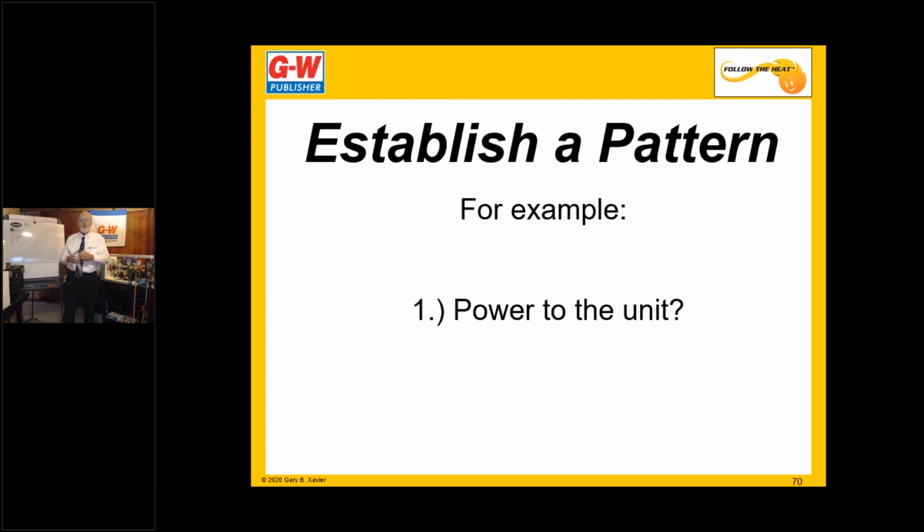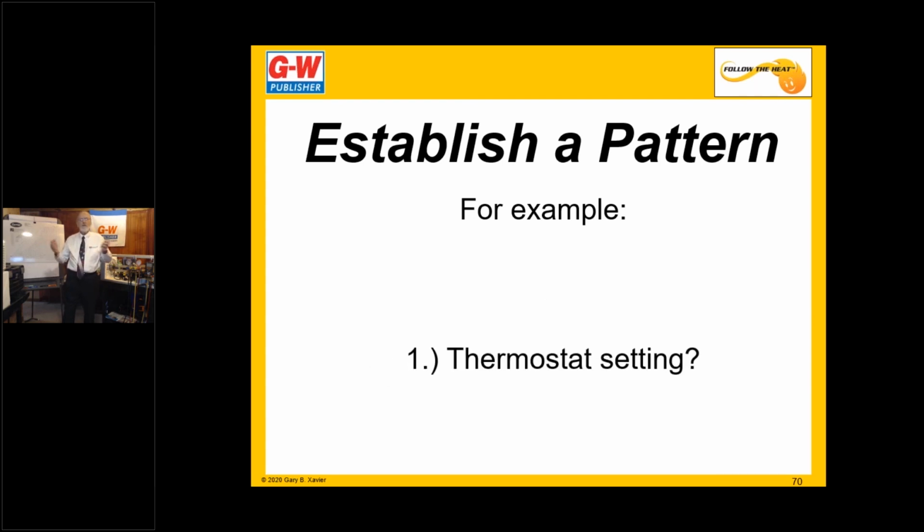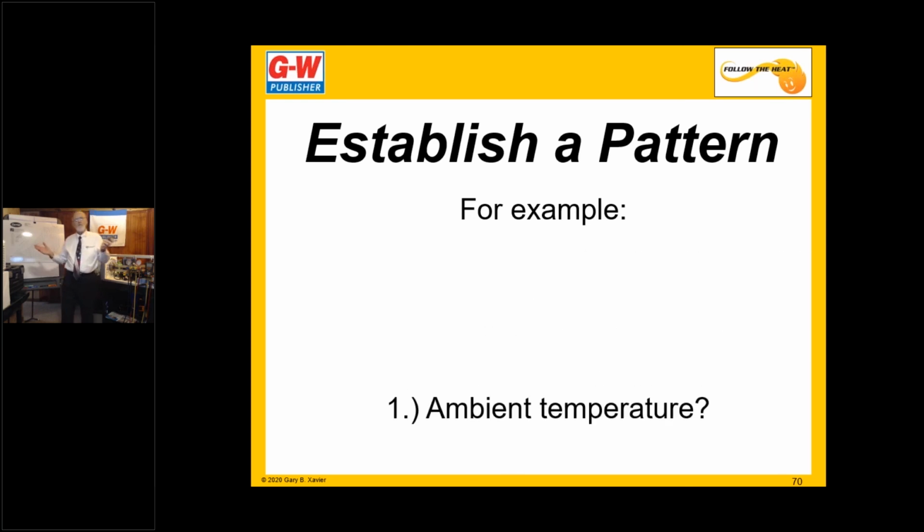Is there power to the unit? What about the thermostat setting? What about the ambient temperature? We want to think of all of these things. These are all things that we want to think about as we establish our pattern for how we're going to troubleshoot, because everyone does it a little bit differently.